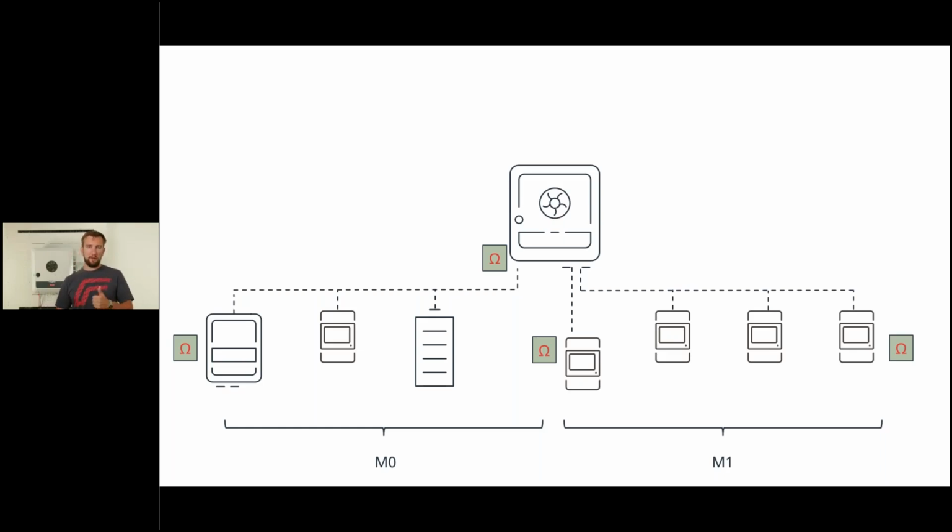So we'll make sure we set the termination resistance. We'll make sure we always know which position our different devices are in, and we'll make sure we don't have too many devices connected on one line, and try, if you can, to even balance the number if you have the availability of using 2 lines, particularly if they're different in geographical location, but also if you're dealing with a high number. If you're at 3 or 4 participants on a line already, consider whether you're going to use the second line if it's a viable possibility from an economic point of view.